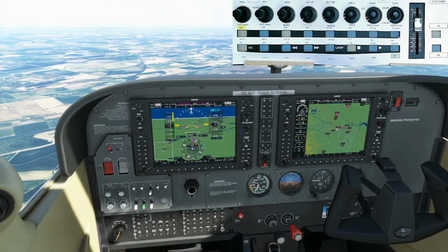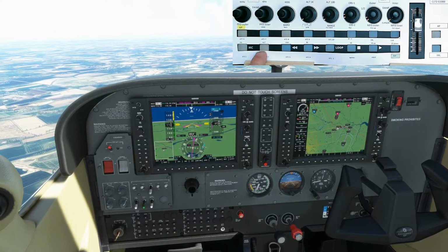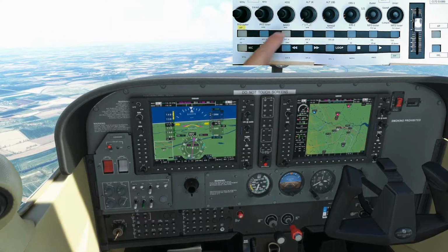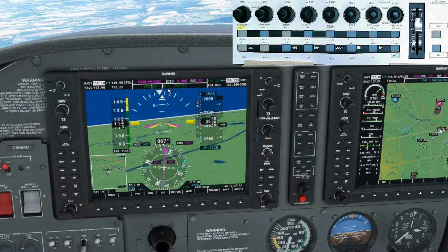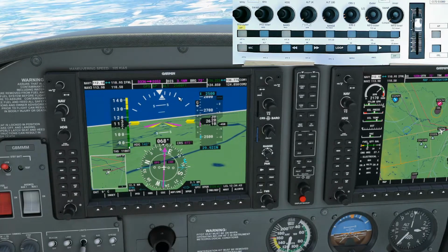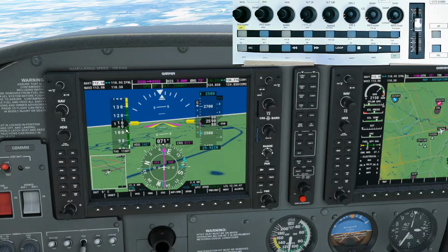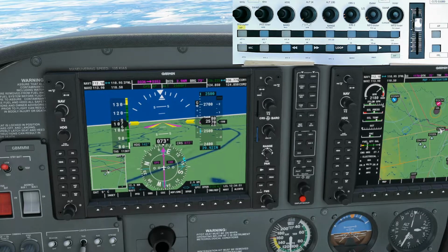Okay, we're coming up on to 2,500 now. And you can see on here it's gone into altitude hold now. It's not on vertical speed anymore. We've now gone into altitude hold, and you can see that on here as well. Altitude hold for 2,500, so it's making the last few minor adjustments. We're losing some airspeed, so a little bit more throttle.